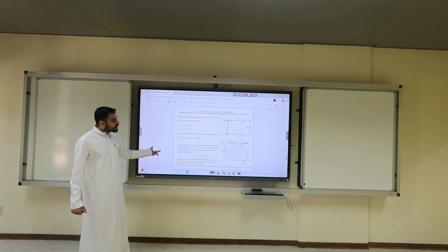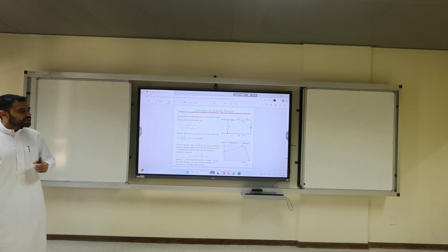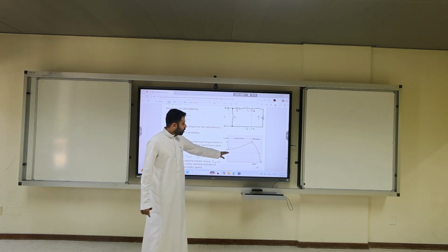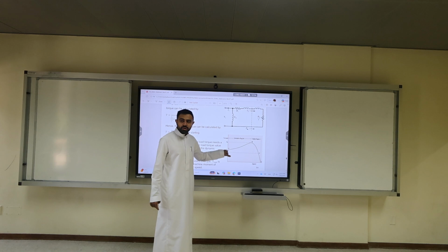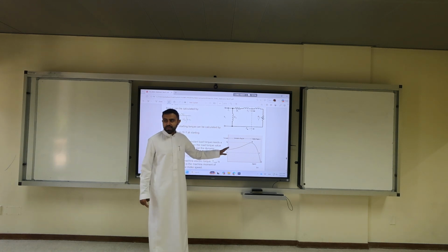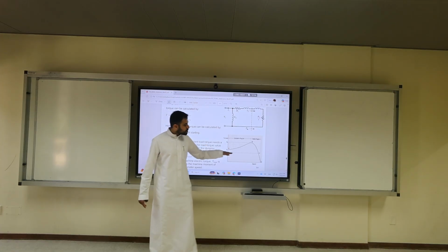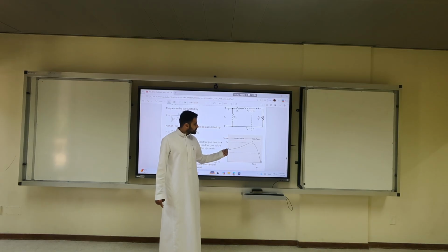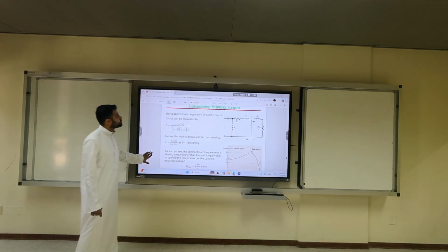So considering the starting torque, do you remember last time I told you that for some applications you want your load torque lower than the starting torque, for applications like the elevator, for example? If you want an elevator, this is class C or class D. Remember class C or class D where we made this up? So for constant torque applications, such as elevators, you have to make sure that your starting torque is larger than your constant load.